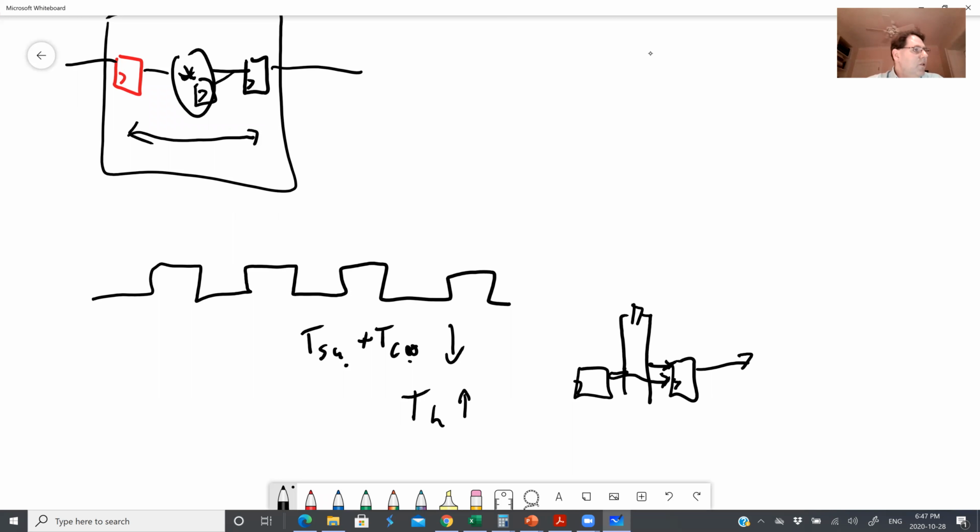If the hold time violations are too many of them and they're too big, then the router's going to have trouble, right? It's going to have problems putting enough extra routing into such a large number of signals that it just can't fix all these problems without running out of routing. But it can fix a moderate number of hold time problems. So this is a case where the relatively slow FPGA routing, where you've got all these multiplexers and so on in it instead of just wires, actually helps you because you're trying to now slow down some paths. And usually you have some extra routing available because you had to build a certain channel width for your difficult to route circuits. So for the majority of circuits, you've got some extra wiring available. Does that make sense?